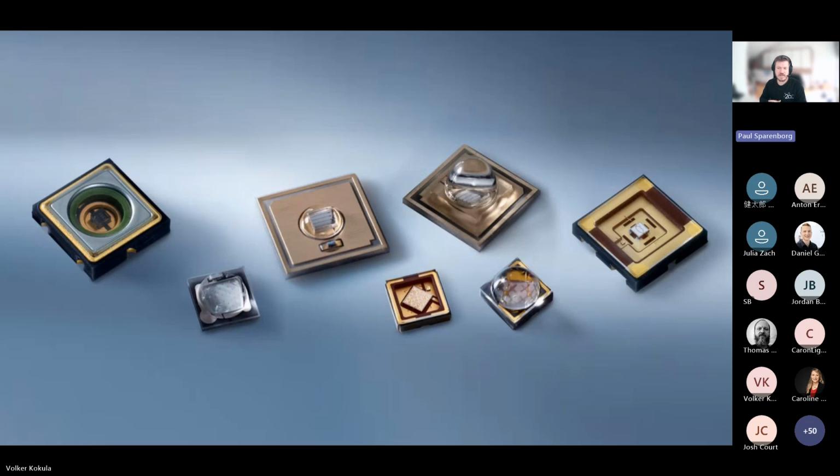We have especially been using flexible PCBs for UV and UVC applications, in which you might know that we still have a very low efficiency on the LED side, which generates up to 95% of heat from the electricity, from the power input to the LED. So very good thermal management is absolutely mandatory, even though in areas of white lighting we have very good efficacy, and the thermal path is not that relevant in many applications anymore.